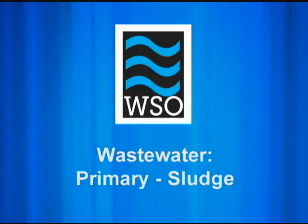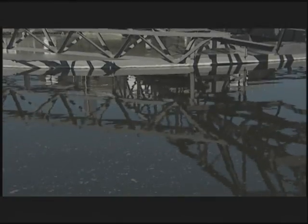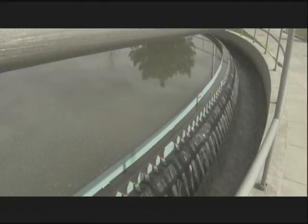The wastewater enters the clarifier, the speed of the incoming water is slowed, and the water evenly distributes around the tank. The point is to introduce the wastewater into the clarifier as quietly as possible. The higher the flow rate, the greater the turbidity, and the greater the solids flowing over the effluent weir, rather than settling out as solids.